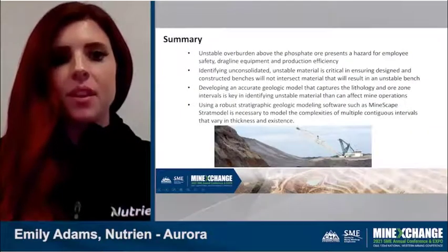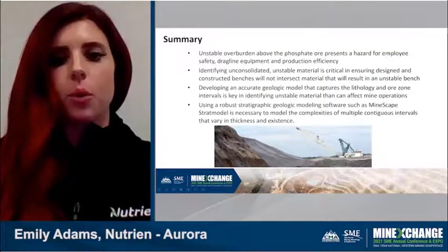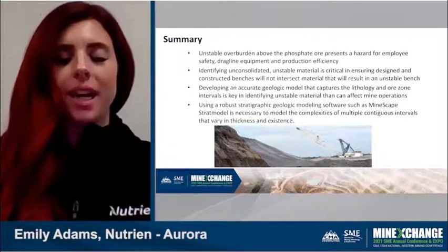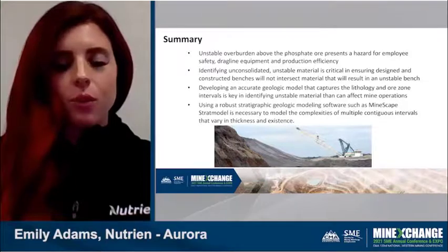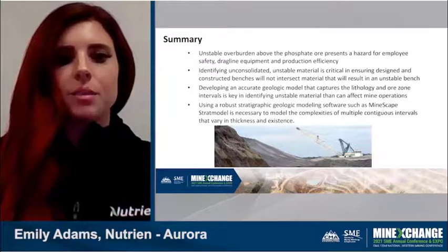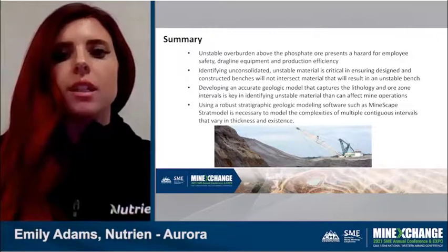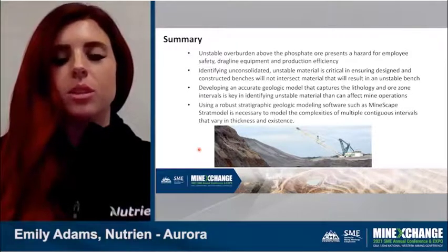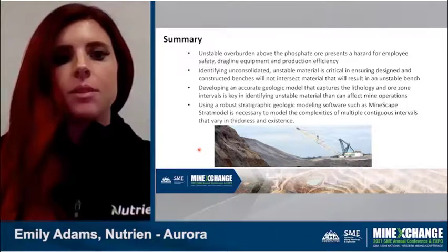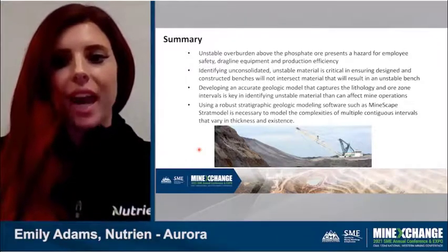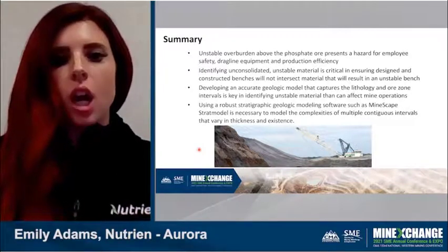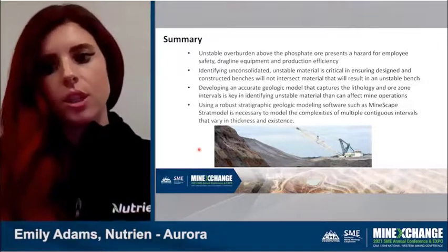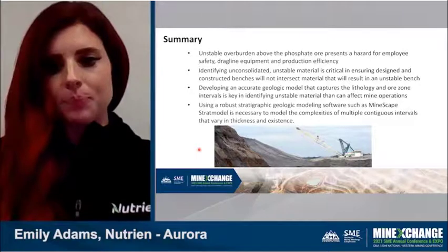Overall, in summary, this unstable overburden above the phosphate ore definitely presents a hazard on the site for employee safety, dragline equipment, and production efficiency. Therefore, it's really important for us to identify these materials. It's critical for us to ensure designed and constructed benches will not intersect material that will result in an unstable bench. Developing an accurate geologic model that captures this overall lithology, geology, and ore zones is key in identifying unstable material, which can impact our mining operations.